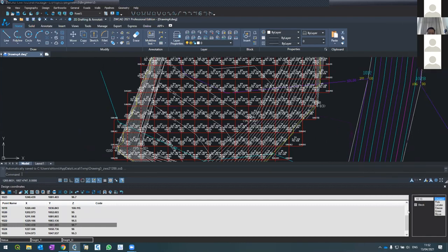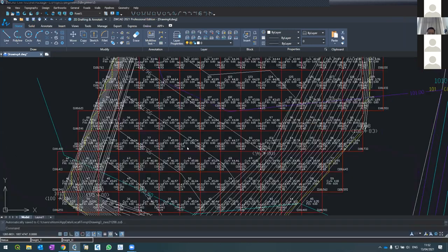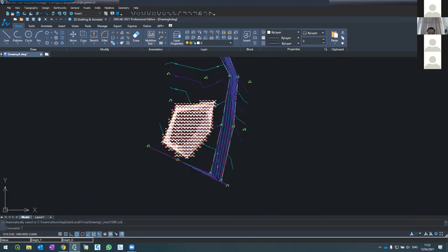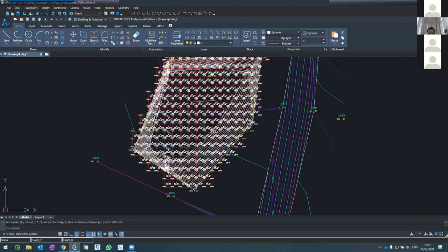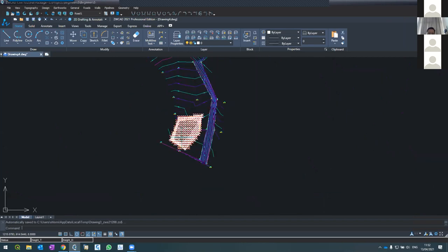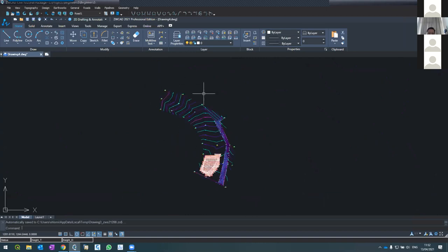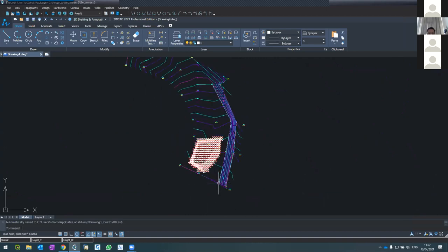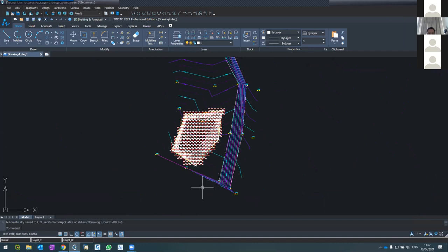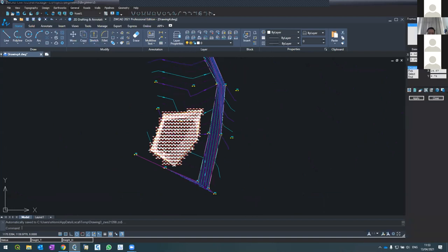Okay. The last method, because we're about to finish the lesson for today, is what we call Frames Maker. Now, okay, I have the calculation. Now I want to put this in a printing with coordinates and everything. How do I do it? In the General menu, I have a tool named Frames Maker. So I'm going to General, Frames Maker. It shows on the right.